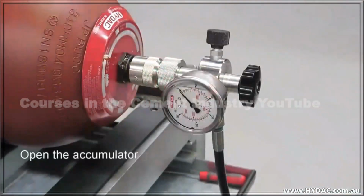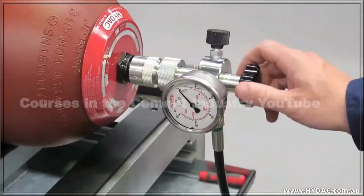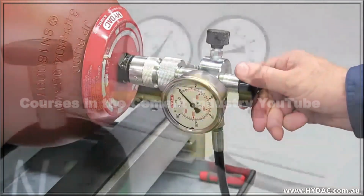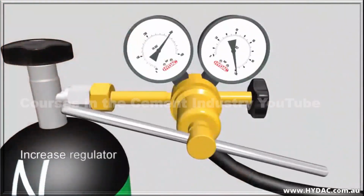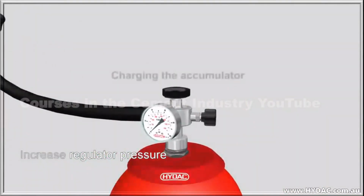Slowly turn the main spindle of the charge head clockwise until you feel a resistance to movement. From this point, back the spindle off about 1/4 of a turn. Begin the gas flow from the bottle to the accumulator by slowly raising the pressure at the regulator.